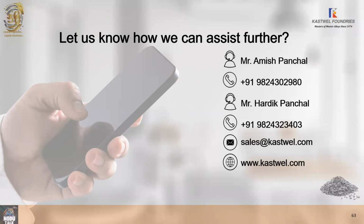Chunky graphite is only caused by the presence of high cerium and high silicon. Take a look at both of these elements, and if the core is crumbling or something, consider giving 2 coatings. The first coating of zircon covered by the second coating of graphite. The coating which comes in contact with the metal should be graphite coating.